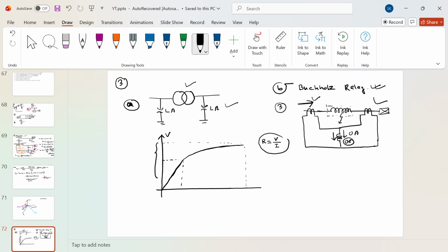So it will detect the internal faults, and so by using the differential protection scheme we use this differential relay. There are some other types, like the percentage differential relay or bias differential relay, but the bottom line is the same: to protect the transformer windings. Also, in the case of a transformer, we use a harmonic restraint relay, that I will explain in some other video.